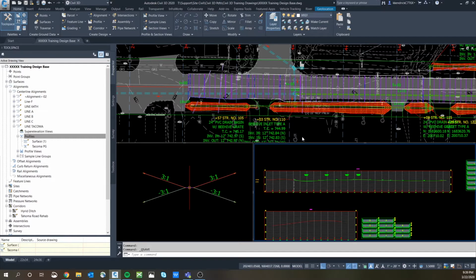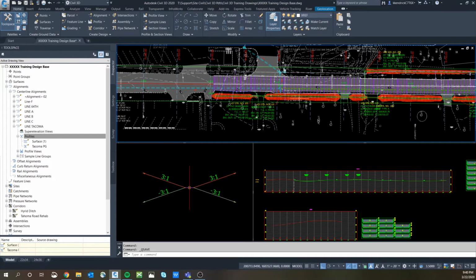If your CAD crashes out because the autosave is trying to go, you're just as danged if you do, because you're trying to not crash by having it saved, but then if it's computing something large when you do the autosave, it crashes. So if you know that nothing's going on, save out. Save early and save often is one of the biggest things to remember working in a corridor.